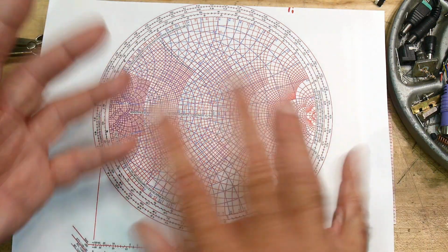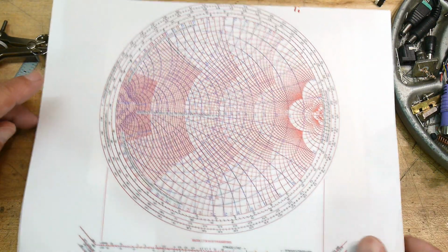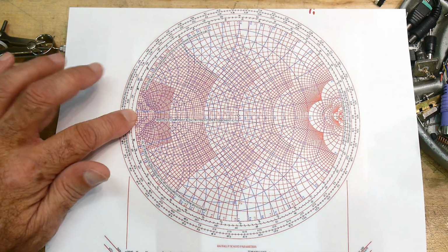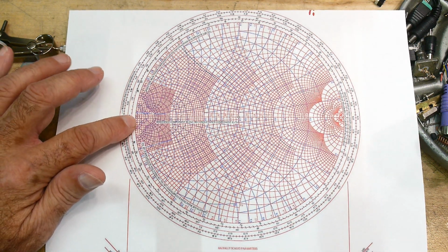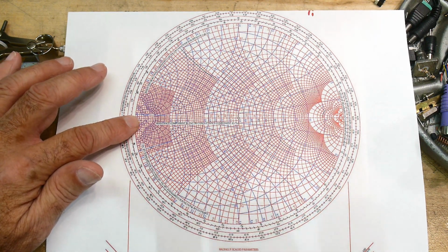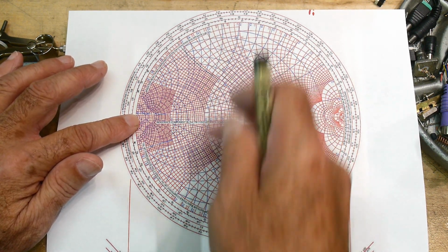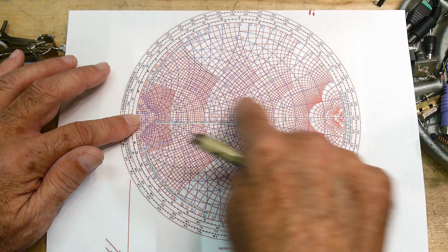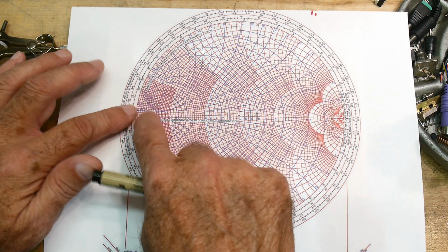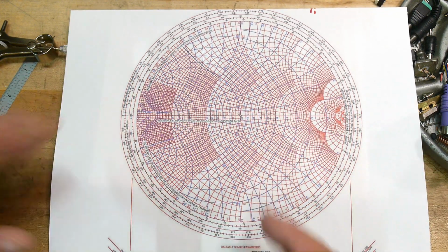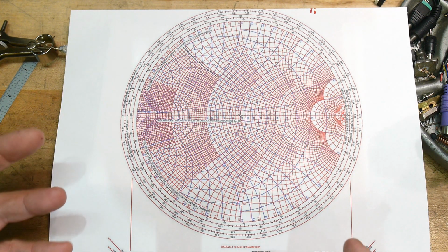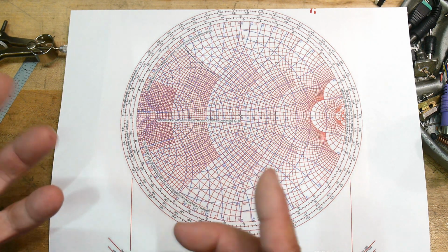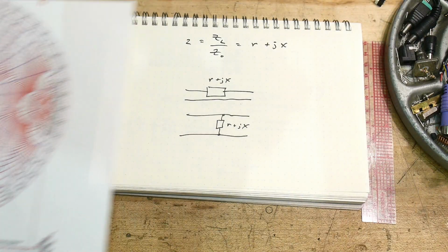We can also plot everything reversed and plot them in blue, and you can see that everything converges on this point over here, which is the short, okay? So this is when things are in short to ground, right, from signal to ground. So you can get shorts here, you can get opens here, and these sets of curves, the red ones and the blue ones, all have names, okay?